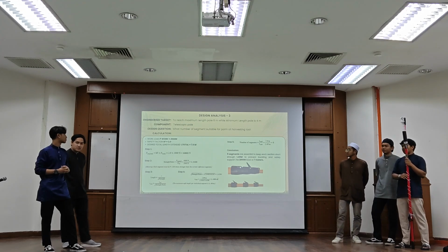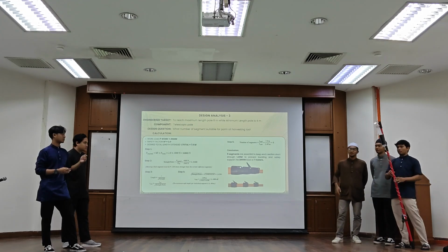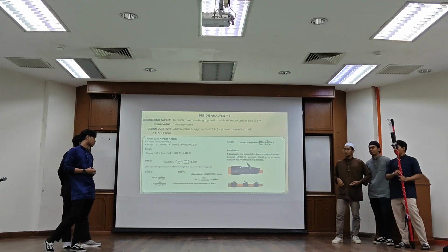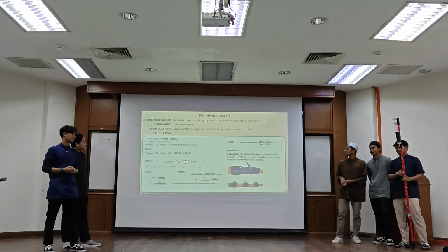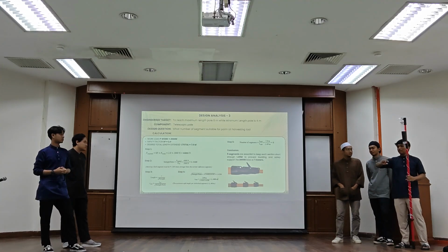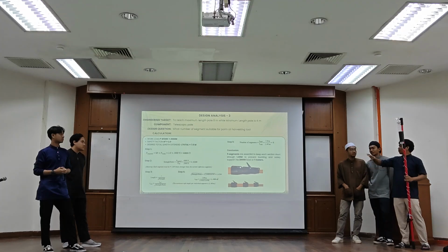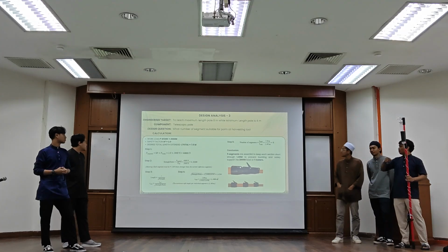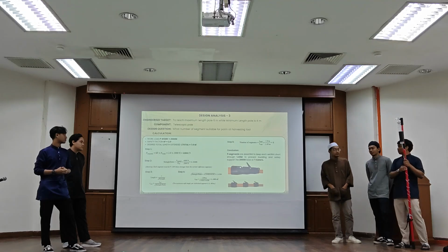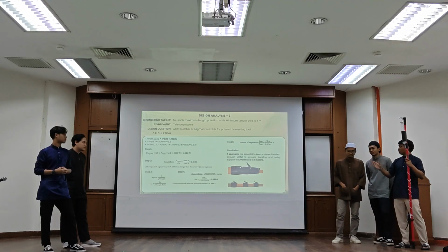Just make sure that this is the shortest, the lowest setting, 4. The longest is 6. You don't need to do much calculating. But if we do only one straightforward 6 meters, it will have less safety factor. It will break the pole, or vibration and so on. We don't want that. So that's why we calculate to find the segments.